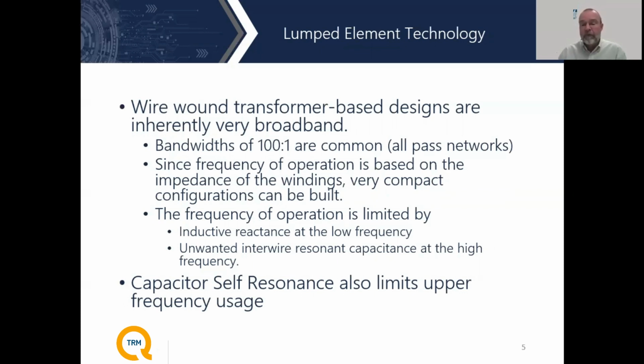The transformers are typically wound on ferrite beads, and these sorts of components use RF transformers as one of the main building blocks for building either a power divider or a directional coupler. The advantage of these sorts of devices is they have extremely broad bandwidths. 100 to 1 bandwidths for some low to medium power devices are very common.